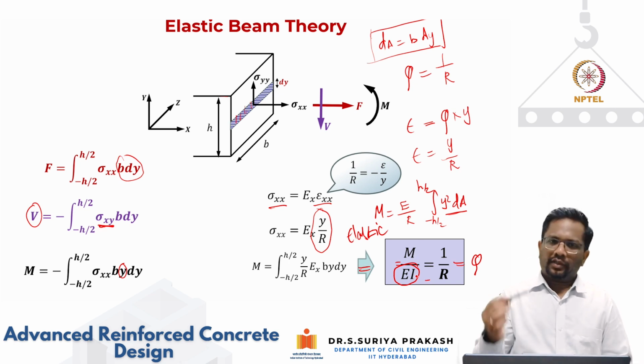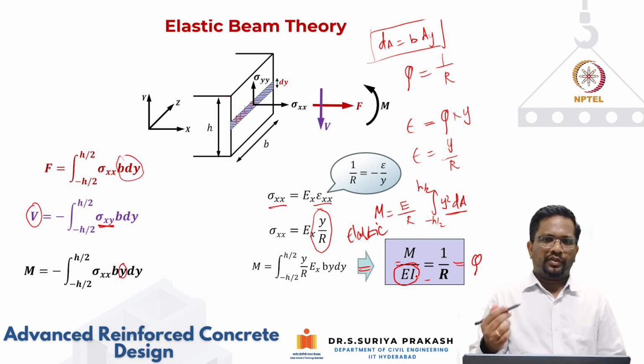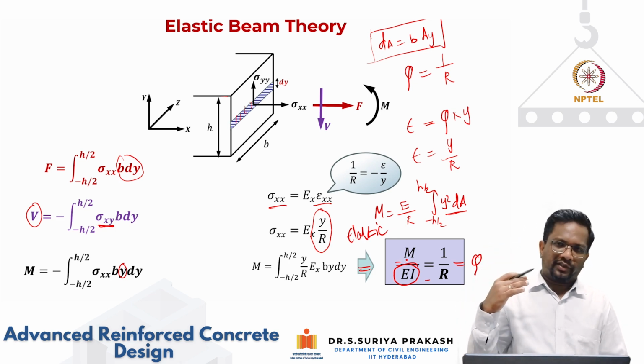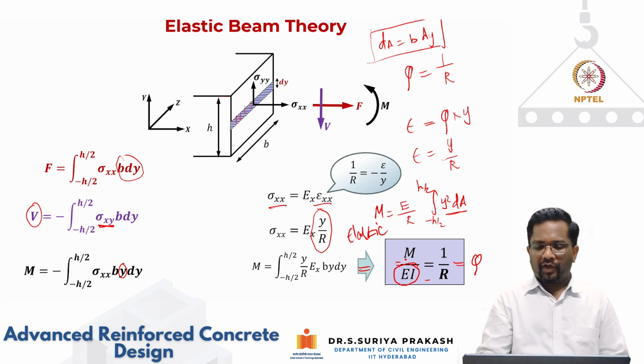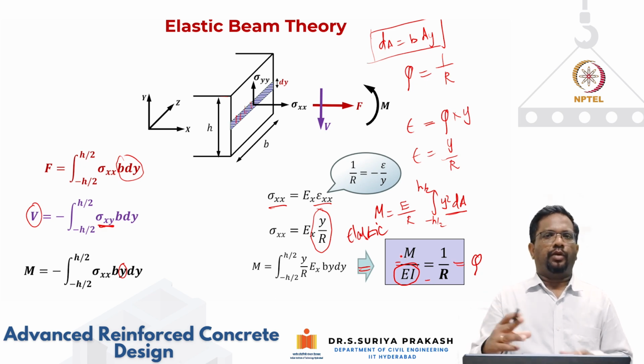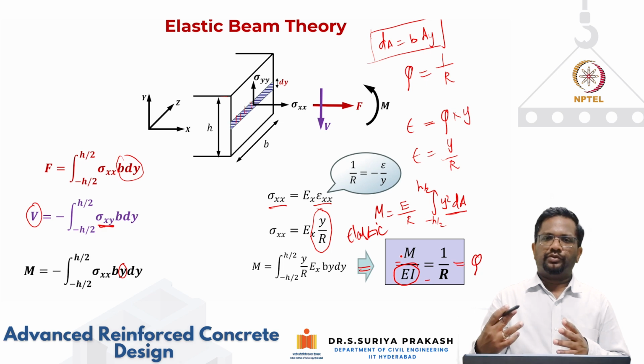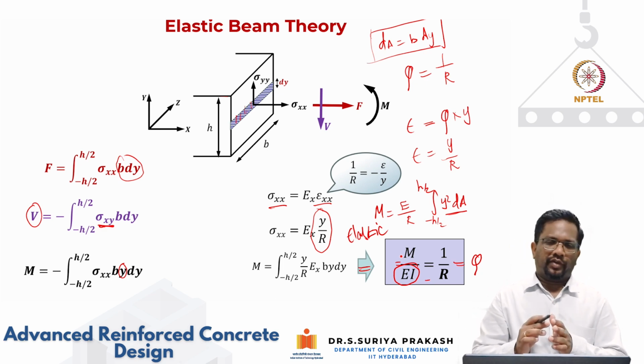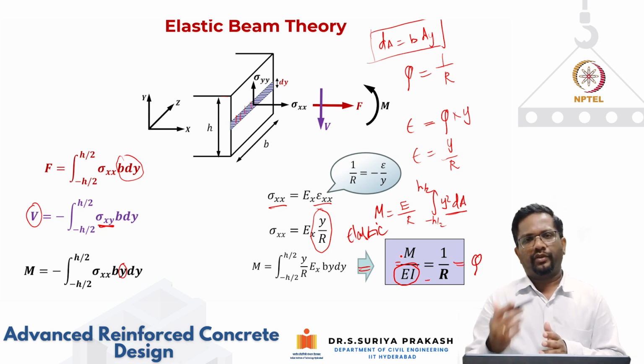In fact, that is what we do in serviceability deflection calculations. Depending upon the amount of moment that a particular section is subjected to, some approximation is given, and the code gives you some formulations to calculate a reduced EI value. EI is also called flexural rigidity.